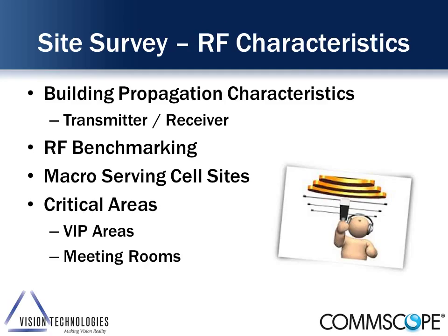Also, if you're in a medical facility that's been renovated over the years, sometimes they've moved the radiology department around. And radiology department implies a lot of lead-lined walls to contain that radiation. Well, if the radiology department has moved, many times the lead-lined walls have not been moved. And so testing with a transmitter and receiver can help validate whether there are any undocumented lead-lined walls in the facility.